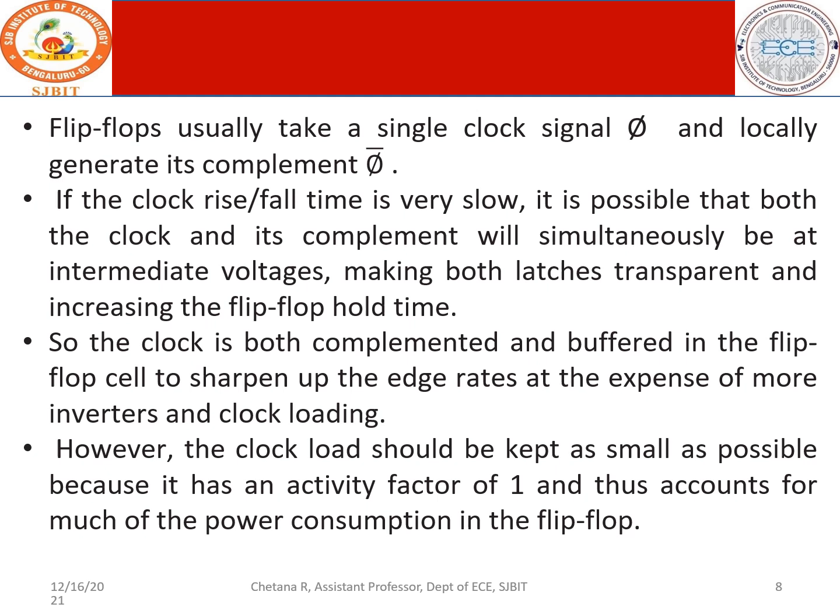So the clock is complemented and buffered in the flip-flop cell to sharpen up the edge rates, at the expense of more inverters and clock loading. However, the clock load should be kept as small as possible because it has an activity factor of 1 and thus accounts for much of the power consumption in the flip-flop.